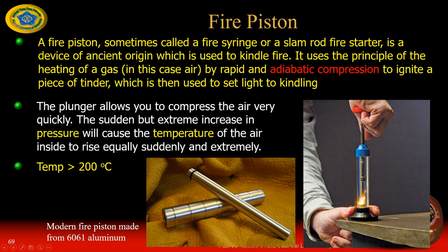So you can make fire using a very simple principle of the relationship between the pressure, volume, and temperature. It's a device of ancient origin which is used to kindle fire. It uses the principle of the heating of a gas, in this case air, by a rapid and adiabatic compression.